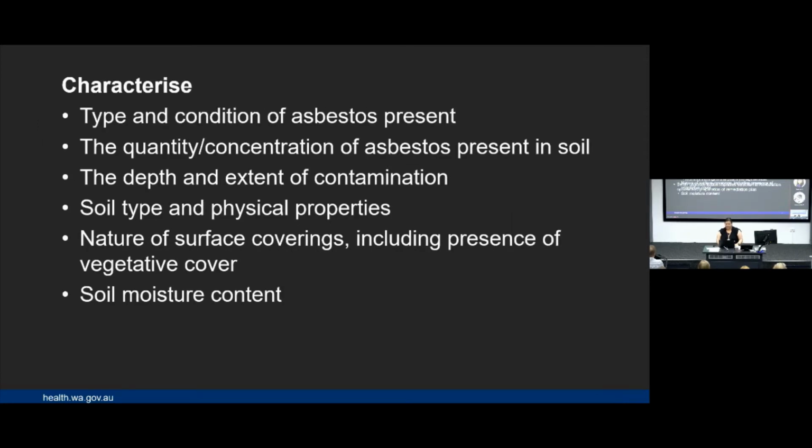Tell us the story. Characterising really is telling us the conclusion of the story you've gone through in your assessment process. What was the type and condition of asbestos that you found? What was the quantity, the concentration of the material that was present in the soil? How deep did it go? How wide did it go? What soil type do you have?